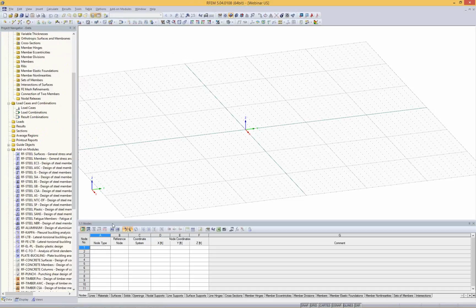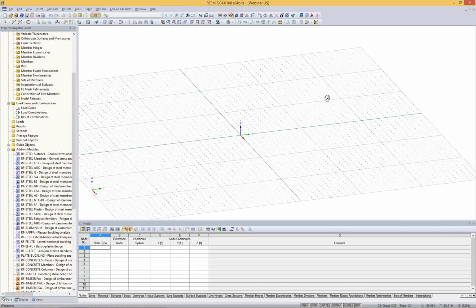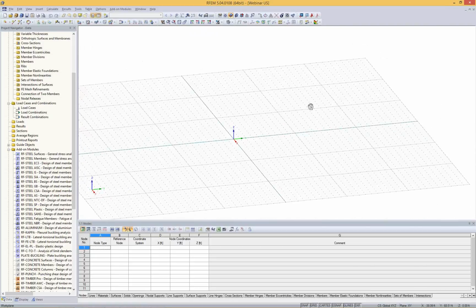On the right lower side, you will see there's a table if you want to prepare, for example, parameters in the structure. You could use this table. And also for Excel export of, for example, internal forces, this tool might be useful. On top, you will see the big screen to prepare the graphic input of the structure.